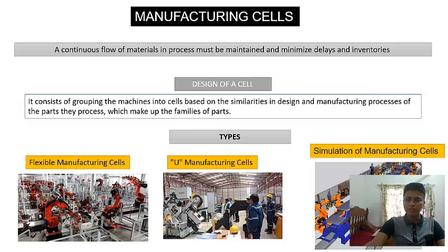In general, flexible manufacturing cells are not attended by humans, so their design and operation must be more precise than those of other cells. The selection of the machines and robots, including the type and capacity of the end effector and their control system, is important for a correct operation of the cell. The probability of an appreciable change in the demand for families of parts must be considered during the design to ensure that the equipment involved has the correct flexibility and capacity.